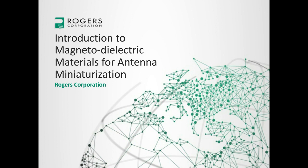Magneto-Dielectric Materials are a newly available class of controlled impedance materials for use in UHF and VHF antennas. They possess controlled permittivity and permeability, both greater than 1, allowing for the materials with a high refractive index to be produced. Numerous publications and measurements also support the ability of these materials to miniaturize certain antennas with minimal impact on bandwidth, achieving designs closer to the fundamental limit of electrically small antennas.